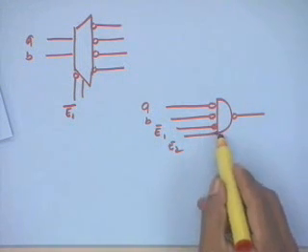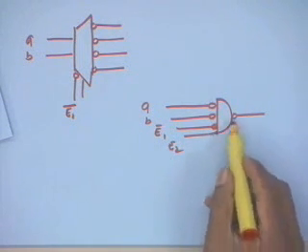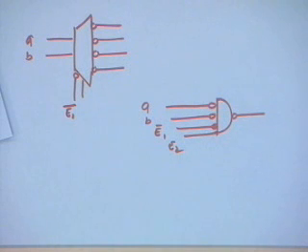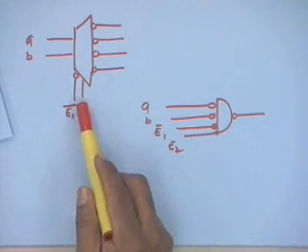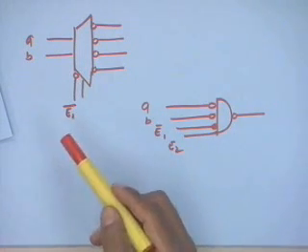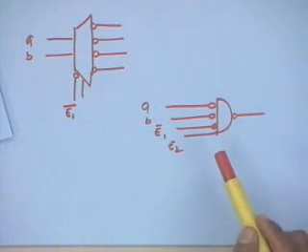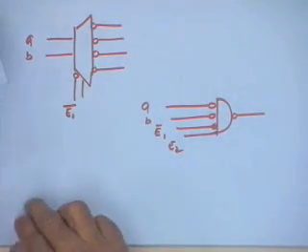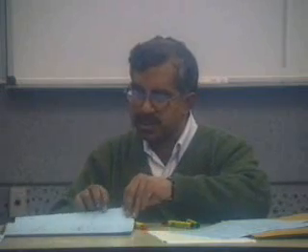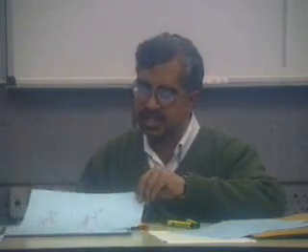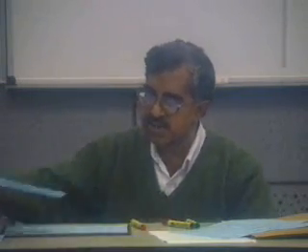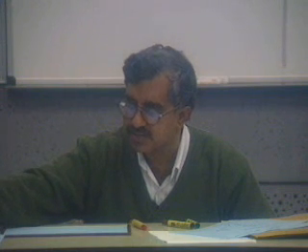So I'm not introducing another level. Of course I am having a 4 input NAND gate instead of a 3 input NAND gate, but because I'm not introducing another level, whereas if I try to do this gating outside, I will have another 2 input NAND or some type of gate, and the output of that will be gated with this. So in this manner, sometimes you can make the circuits faster by providing multiple enables.